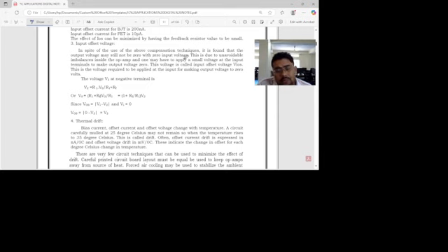Even when we apply zero voltage to both input terminals, the output will not be zero. This is due to imbalance of the transistors inside the op-amp. Even though we have applied zero input voltage to both the inverting and non-inverting terminals, it creates some output voltage value. That value is called the input offset voltage.